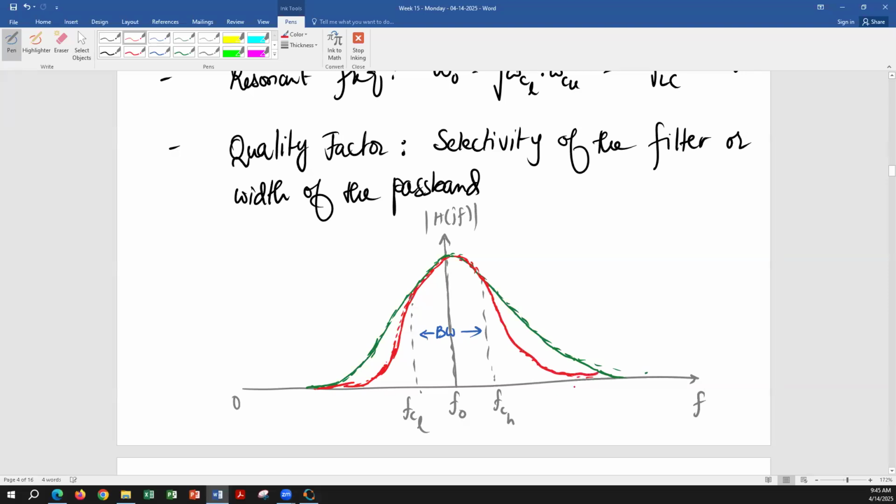So now you have another bandpass filter, and it has the same bandwidth, because bandwidth is between the two cutoff frequencies. But now the transition is not as wide. And then you can have another filter that can be even sharper. That can go something like this.